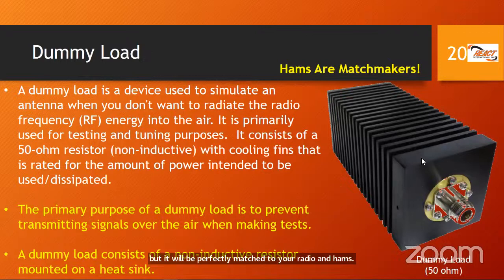Also, what does it consist of? Well, that's another exam question. A dummy load consists of a non-inductive resistor mounted on a heatsink. So let's dissect this point here. So this is our dummy load here. What does it consist of? Non-inductive. So remember when we talked about an inductor? So we're saying this is non-inductive. What do they mean by that?